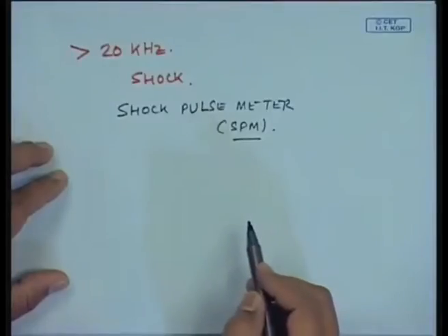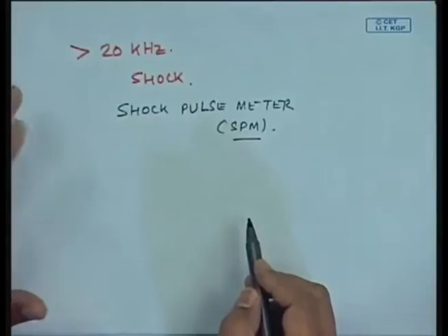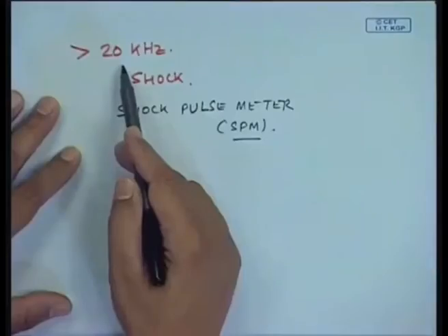It is not the normal operating functionals of a bearing, but it is if there is a defect like a pit, like a defect in the inner race, outer race. Because of this pit I am getting an impulse and this impulse's frequency response is a wideband response which has excited the right hand side of the equation. So, I am getting large motions at the resonant frequencies of this bearing, and as the bearing designer they always make sure that the bearing's natural frequencies are not in the operating frequencies of the bearing and they are at frequencies much higher than the operating zone, usually of the order of 20 kilohertz.